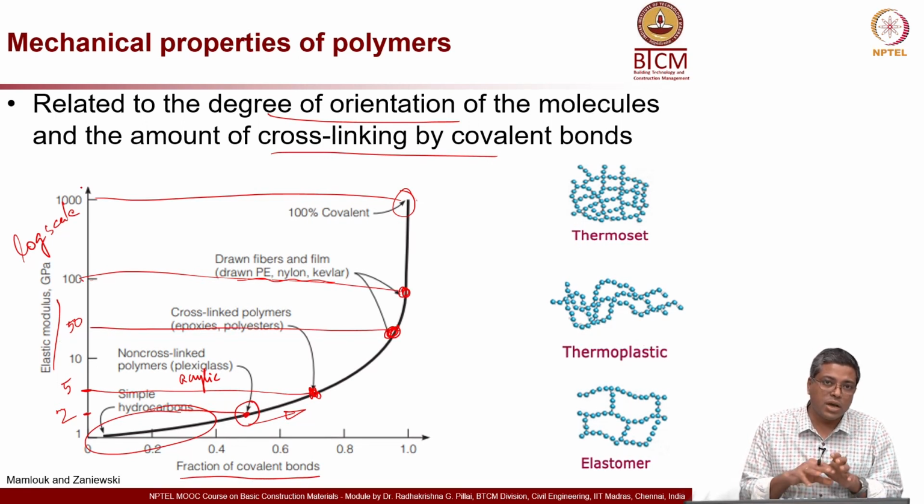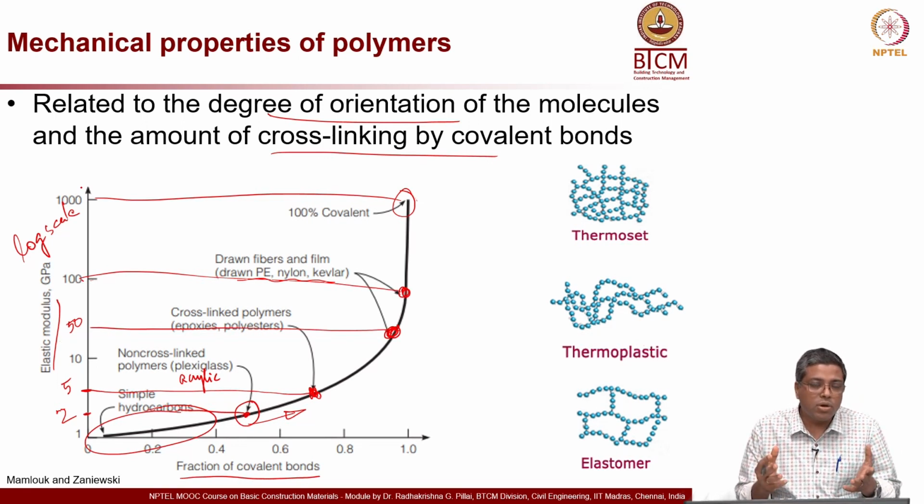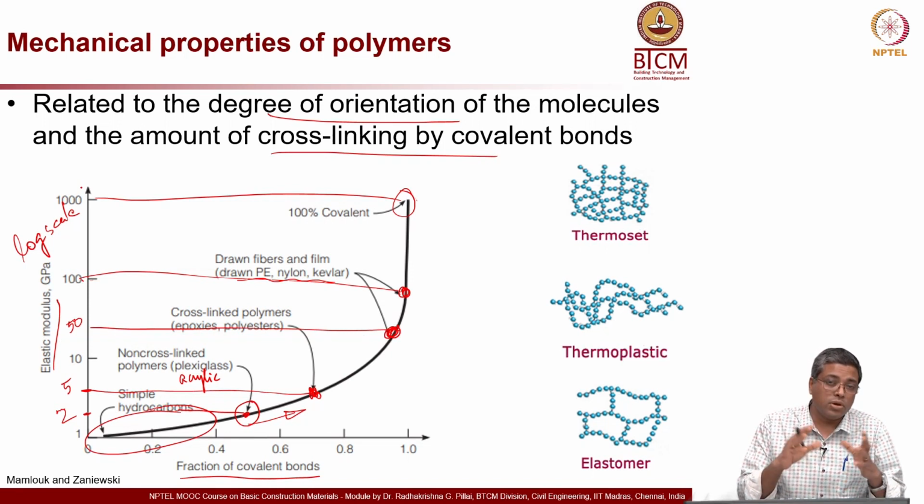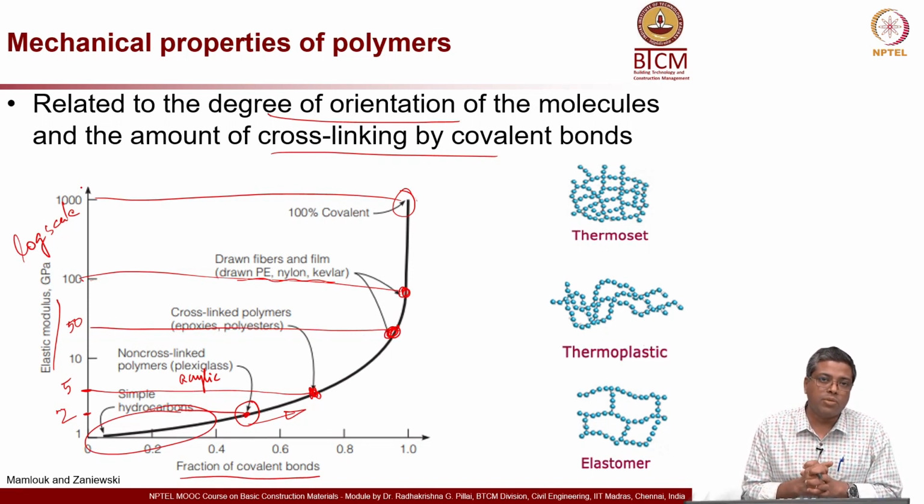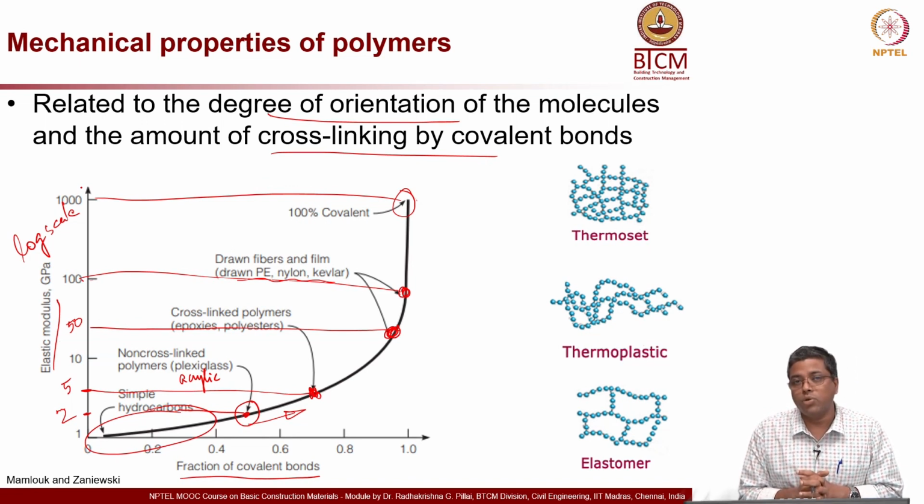If it is going to be covered, then it might be okay, it might last longer, but if you are going to use it for an exterior environment where it is directly hit by sunlight, etc., you will see that if it is not UV resistant, it will become brittle very fast, and it may not be good for the structure.